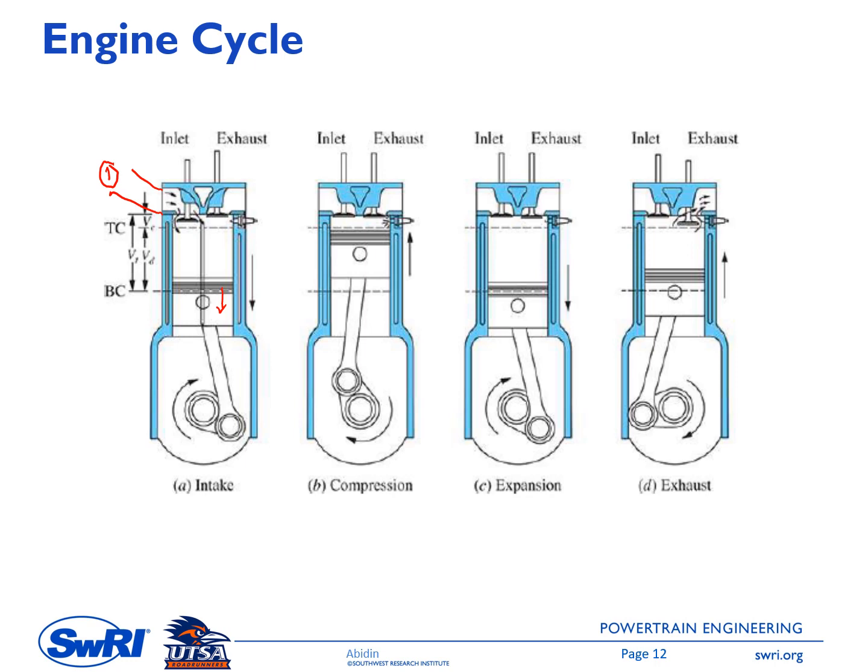So during the compression stroke, the piston moves up, and you can see in here the intake valve is closed. So it means a closed system, okay, a closed system. It means a control mass, the mass stays the same. So there is no mass flow in and out during this compression stroke. Therefore, the mixture is compressed by this piston movement toward top center.